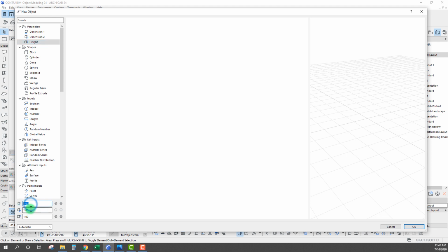Quick note here, this is only available in meters. So you'll notice, as we start creating objects, that if it's set to 1 by 1 by 1, it's going to be a little over 3 feet by 3 feet by 3 feet. And so you'll want to take that into account if you're working in imperial units, and you can always go in and adjust those later in the settings.